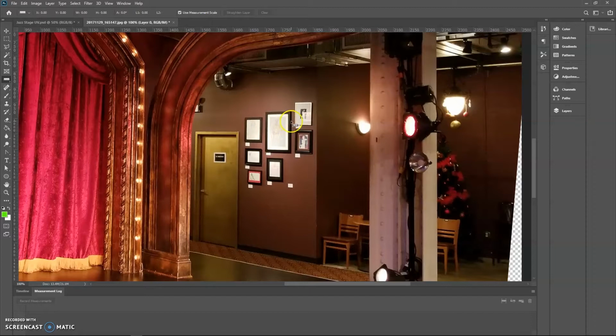The other thing I need to do, so it's fairly straight, is I need to measure this door and set the scale for this door, and we can get some approximate numbers. So most of the time these doors on average are 80 inches. So I'm going to drag that right there.